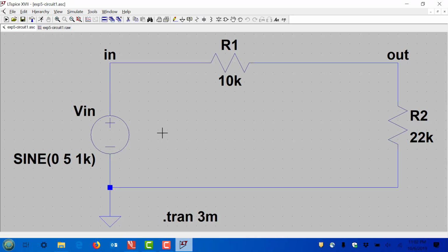So this is a circuit. Go build it. And there are steps for you to set up the circuit: first set up V in by hooking up directly to the scope, making sure it is what it is, and then you connect it to your breadboard. And once you have it in your breadboard, then you will measure V in and V out by hooking these 2 points to the oscilloscope. So instead of just measuring with a multimeter, we're going to look at the waveforms of these signals, V in and V out.